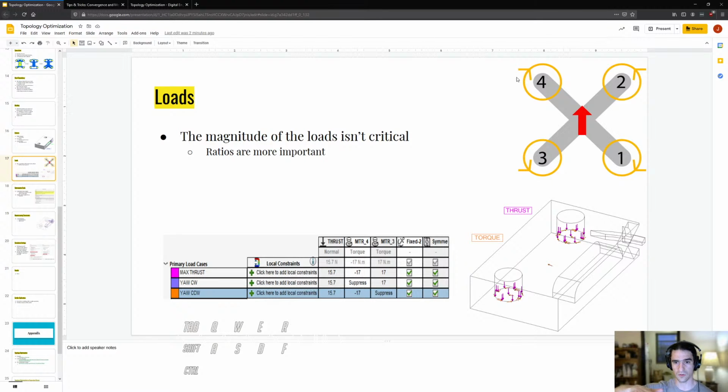Getting it to roll and pitch is just slightly more complicated. If you look at the diagrams that I've got up here, to roll to the left, you would spin up props 1 and 2 and decrease on 3 and 4. So you're going to rotate to the left. And similarly, for pitching back, you'd spin up 2 and 4, decrease 1 and 3, and pitch back.